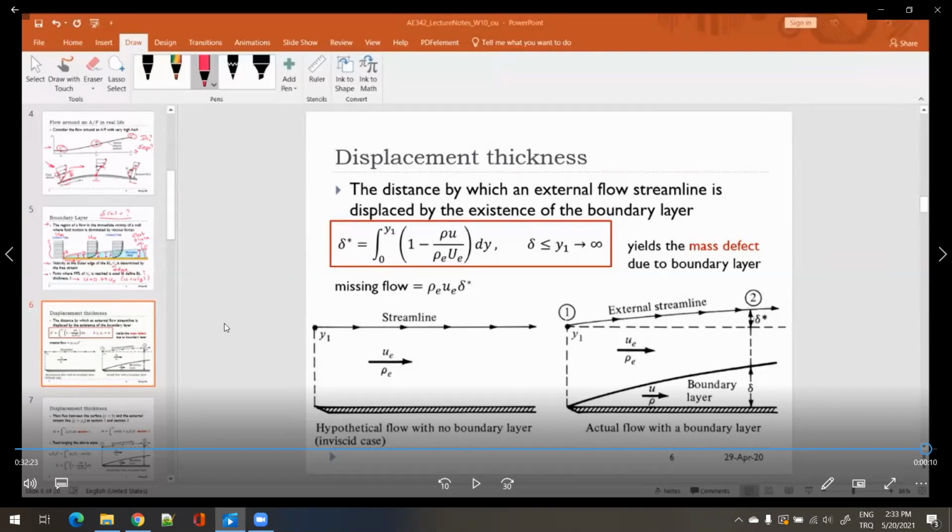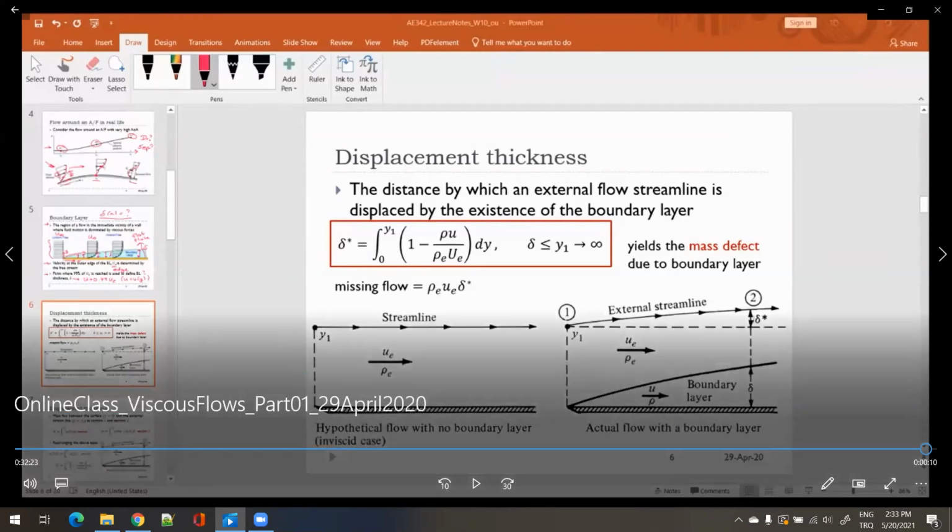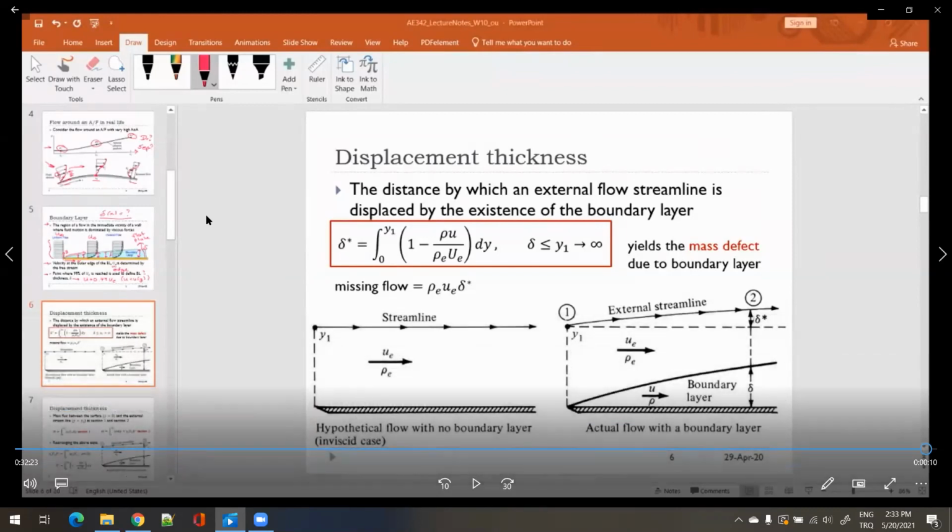Yes, I'm listening. Can I ask something? Of course. We can see the acceleration of the flow on the upper side of the airfoil, cambered airfoil or symmetric airfoil, if it has an angle of attack. Yes. So the flow turns from subsonic to supersonic, if, let's say, you are above M critical, yes?